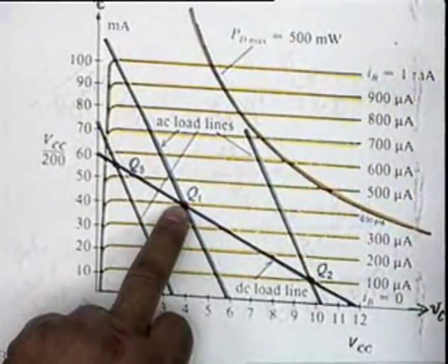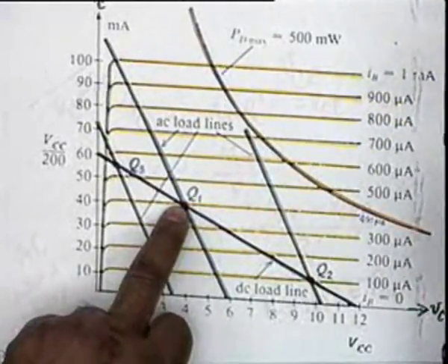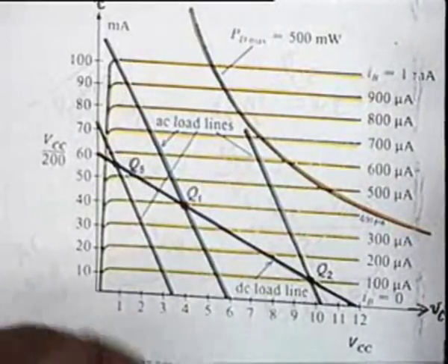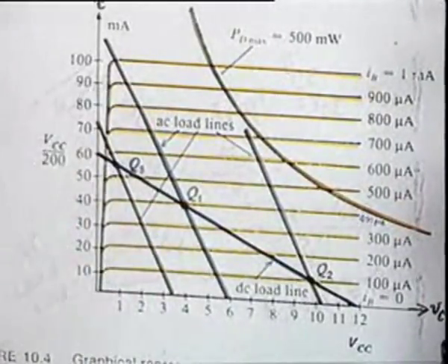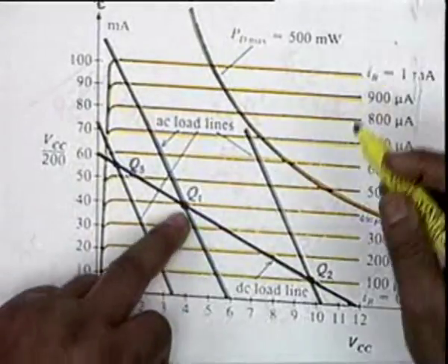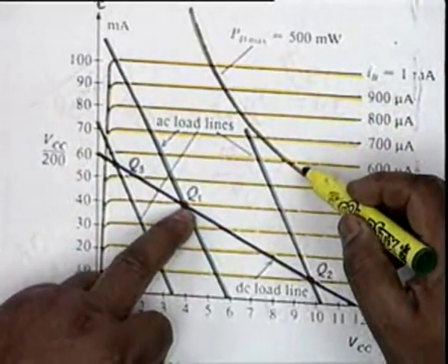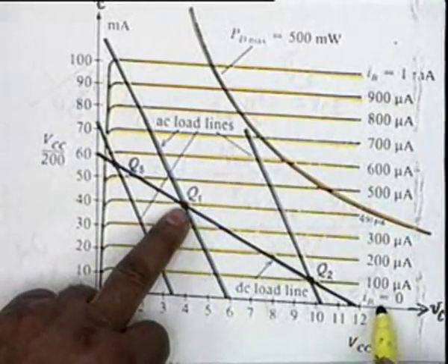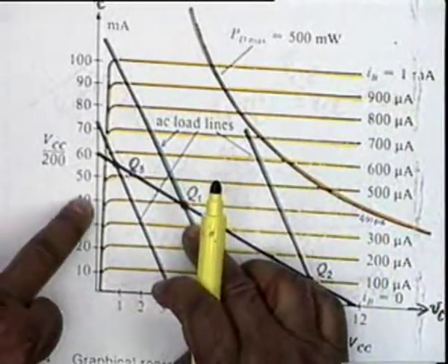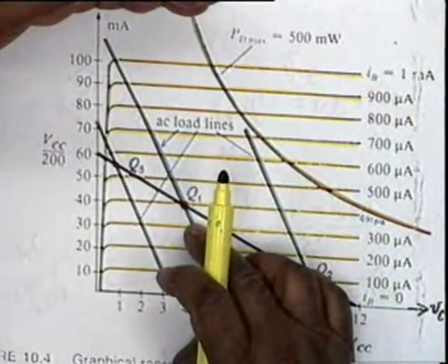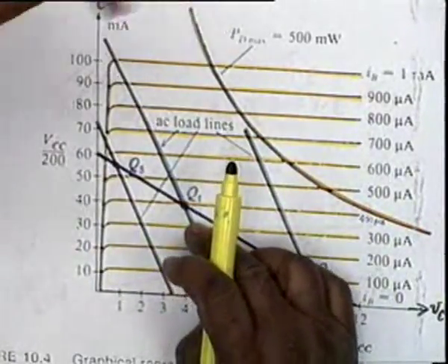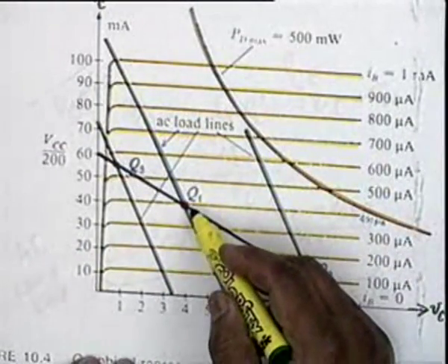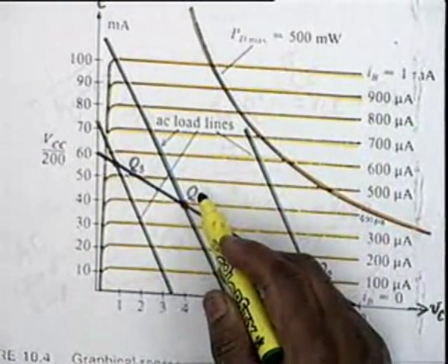But then if you want symmetrical swing, you should be limited to 80. That's right. So between 0 and 80. So this is a very good operating point. It's quite far away from PD max, so you are safe. It's far away from 30 volt. The current 40 milliampere is far away from 800 milliamps. So this denotes the AC load line and a safe operating point.